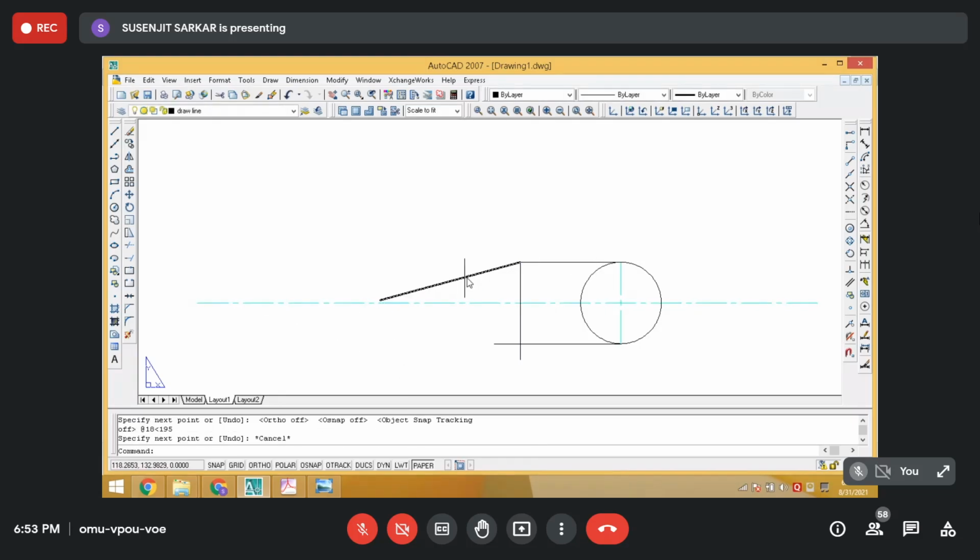I've drawn this line. I have to make a copy of this, a mirror copy. So this is the mirror command. Click mirror. Select this one. Confirm it. Then specify the first point of the mirror line, because I want a mirror about this line. Make snap on.